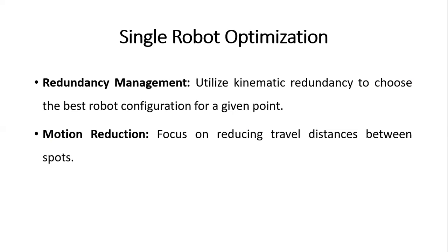By using the basic kinematic motion path planner option, we can identify the best robot configuration that can be utilized for a specific production job operation. Accordingly, we can find out the possibilities of motion reduction by aiming for reduced travel distance between the two nodal points.